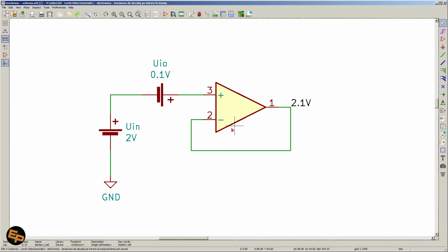However, of course, it will have a big effect on an actual amplifier that has an amplification factor, because this input offset voltage will get translated into a much bigger output offset voltage, because it will get multiplied by the amplification factor of that particular circuit. And that is, of course, a problem.